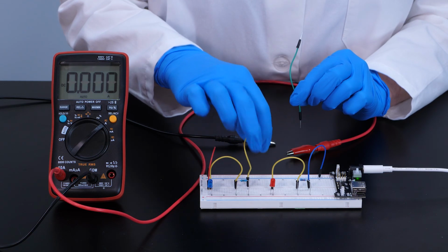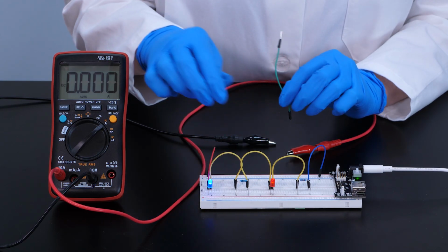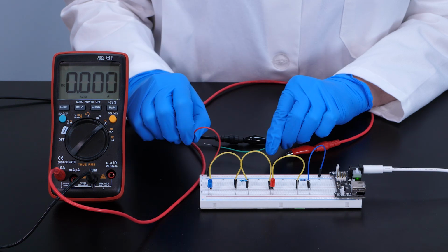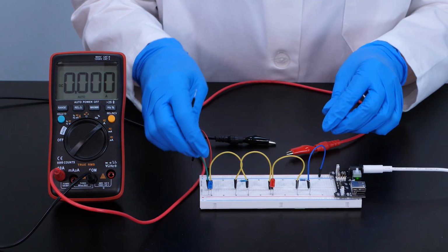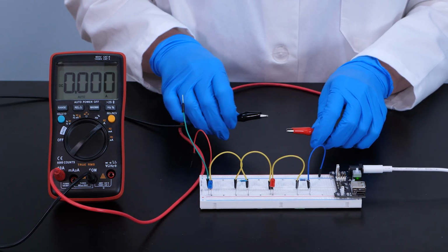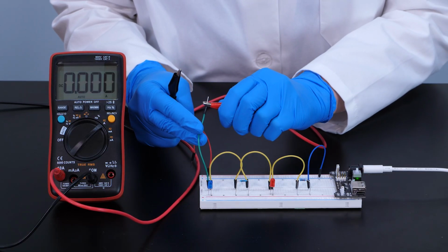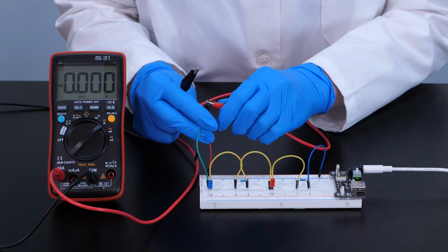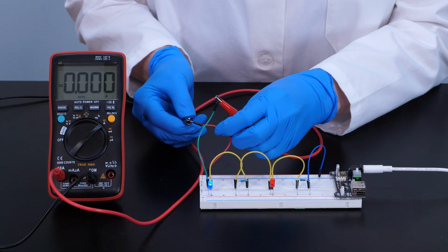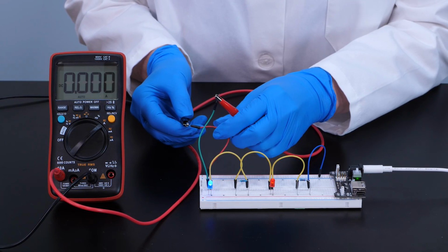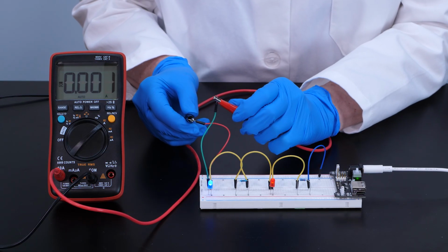To measure the current through the second load, we replace the yellow jumper wire and then unplug the red jumper wire in socket 61F. Then we plug a green jumper wire into the socket where the red jumper wire was plugged. Notice that both LEDs are turned off. When the exposed ends of the jumper wires were connected to the leads of the multimeter, the circuit was closed again, so both LEDs are back on. We see that the current flowing through the second load is 0.001 amperes, which is the same as the current flowing through the first load.